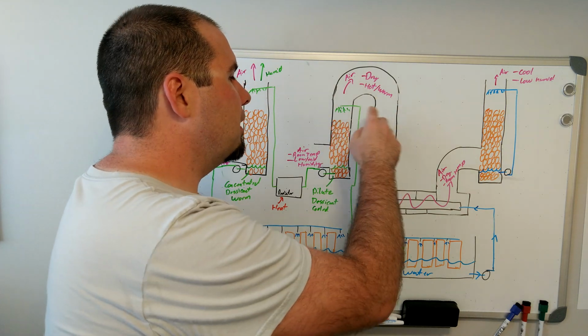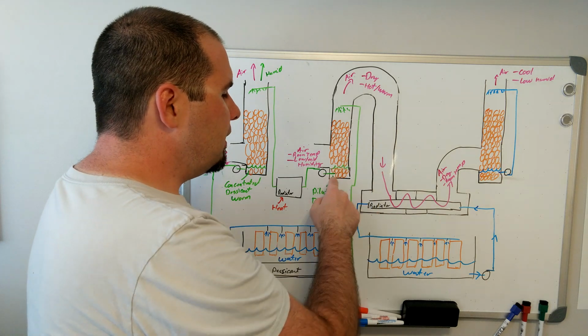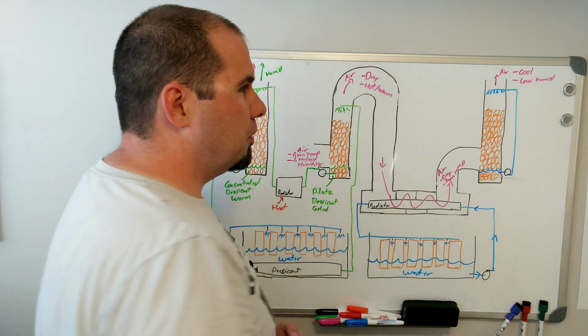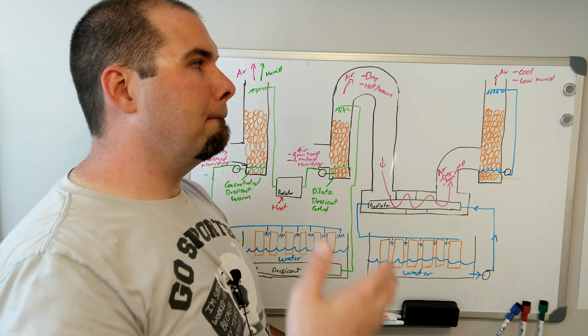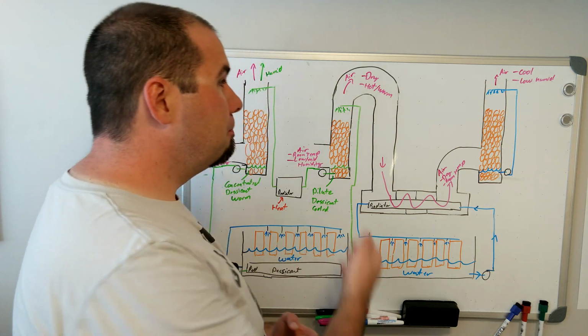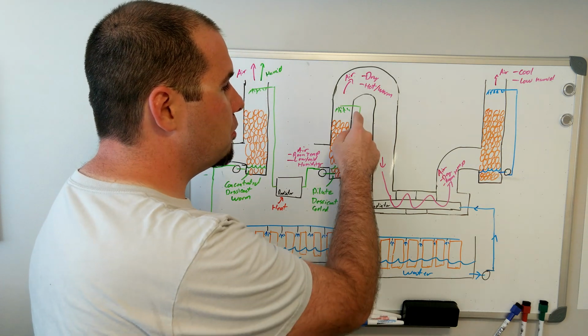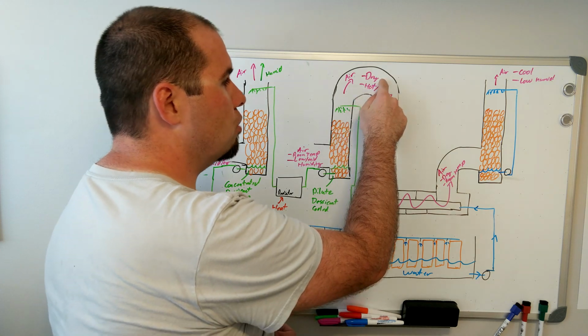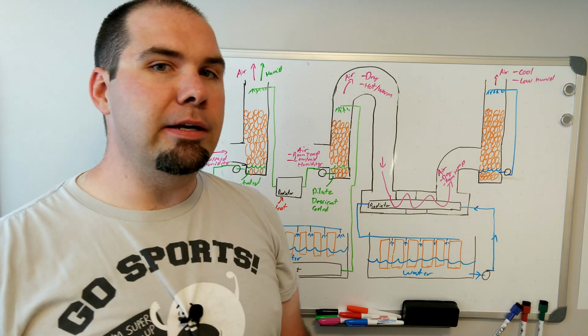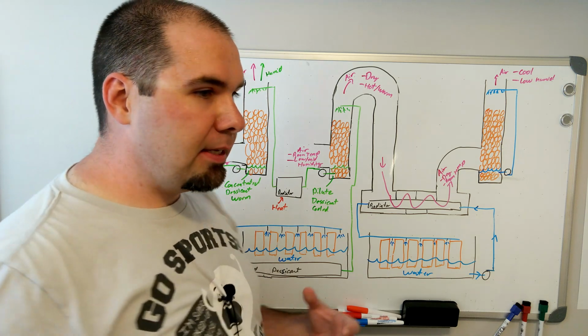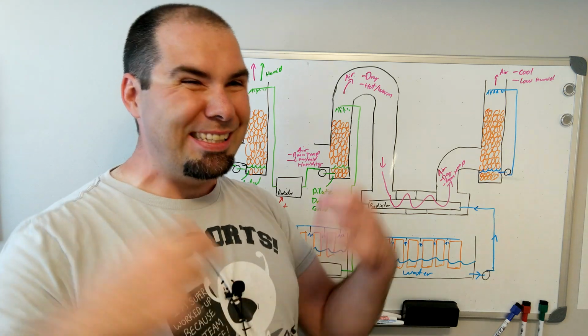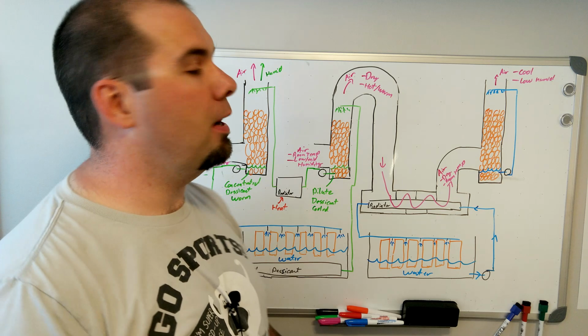So it's actually warming up there. Normally we're expecting out of this loop, we would get cool but humid air. But what we're actually getting is the reverse when we use a desiccant. We're getting dry but hot air. So that desiccant reaction is releasing a lot of heat, but taking away all that water.